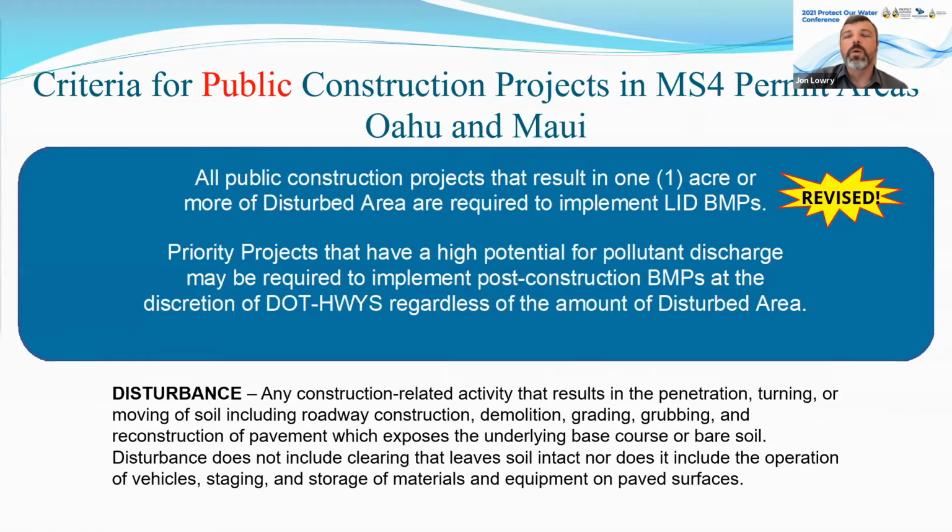So here's one of the larger changes to be aware of. This is a criteria specifically for MS4 permit areas. And I'll back up just a bit. There are areas on Oahu, all of Oahu and City and County of Honolulu, island-wide on Oahu, that are covered by an MS4 NPDES permit. The areas there are the more urban areas of Maui that are covered by an MS4 NPDES permit, but for the purpose of this manual criteria, the entire island of Maui is included.